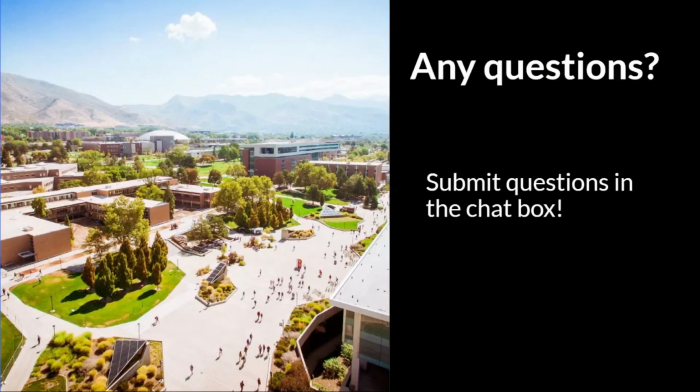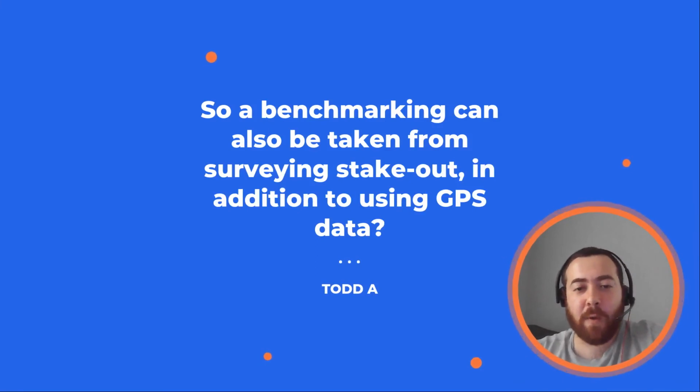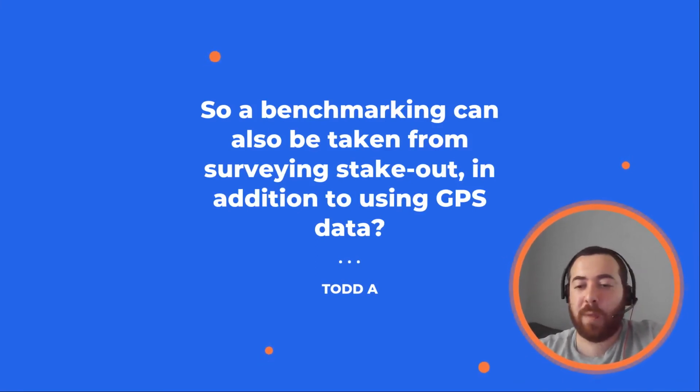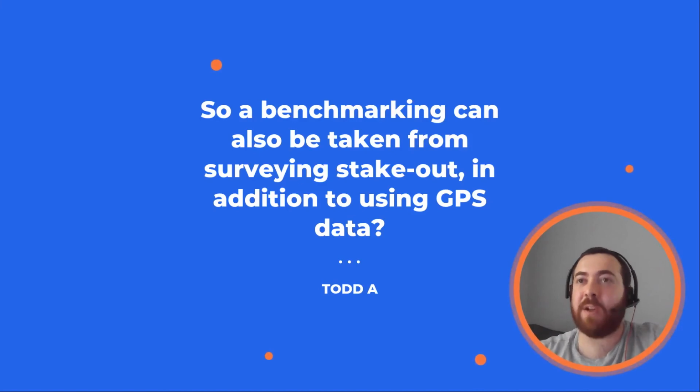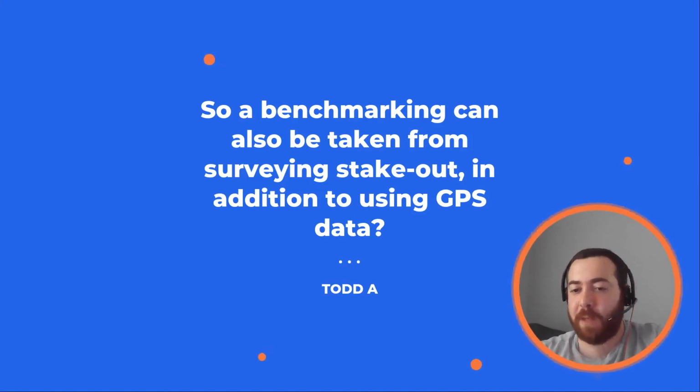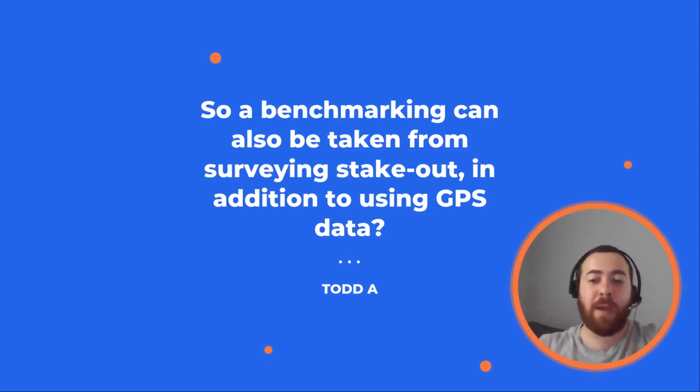All right. I don't see any other questions right now, but I just want to let you know we do offer a. Yep, saw one more just come in. So benchmarking can also be taken from surveys. Yeah, you can use survey data as well. We can incorporate survey data into your point cloud, and what we do is we actually have what we call tags. The tags can be placed on projects, and essentially they work very similar to GCPs. You can survey your GCP, you can survey your tag, take that GPS location, integrate it into your model, and there you go.